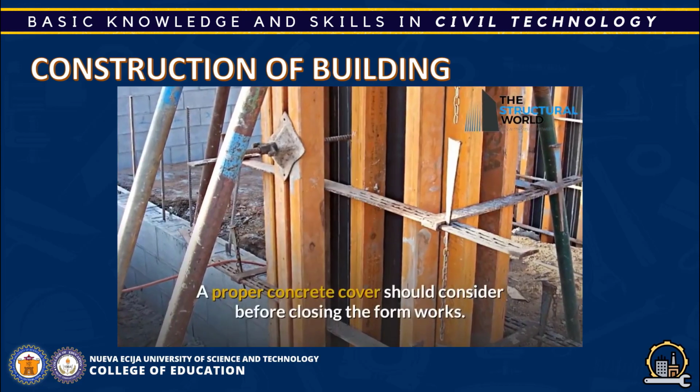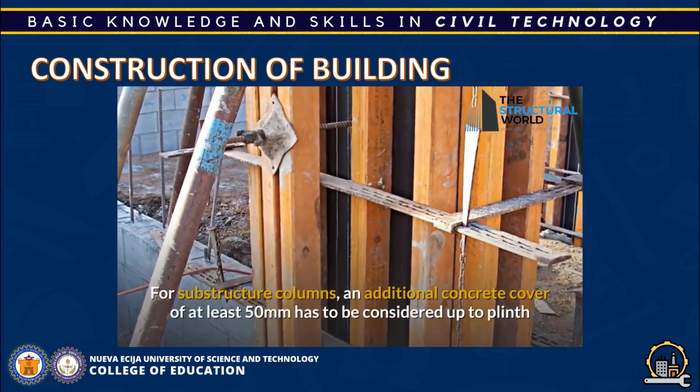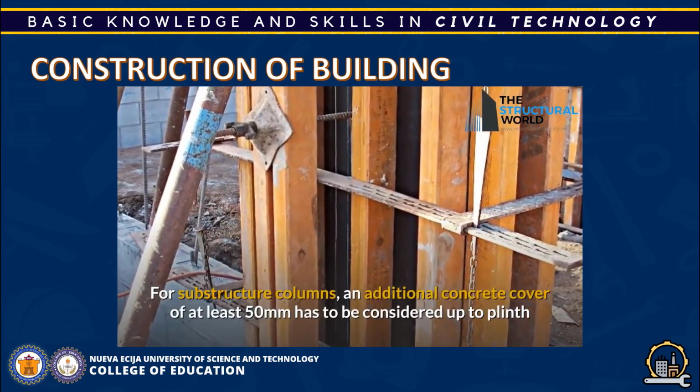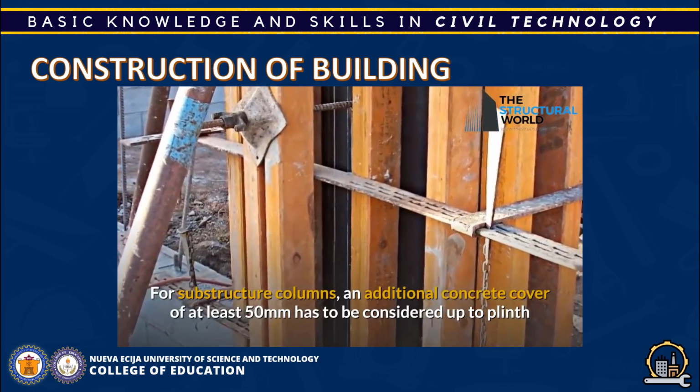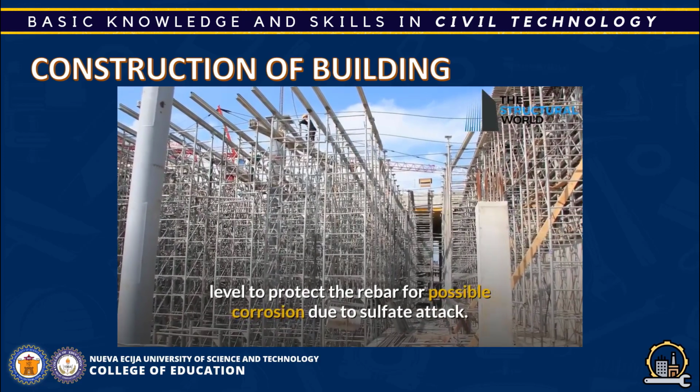A proper concrete cover should be considered before closing the formworks. For substructure columns, an additional concrete cover of at least 50 mm has to be considered up to plinth level to protect the rebar from possible corrosion due to sulfate attack.